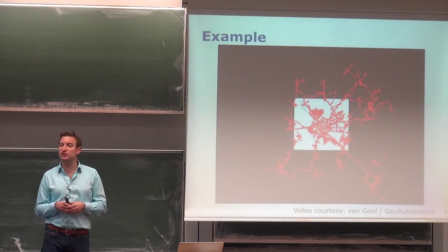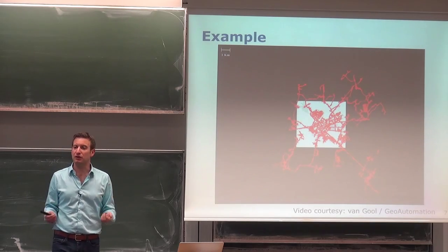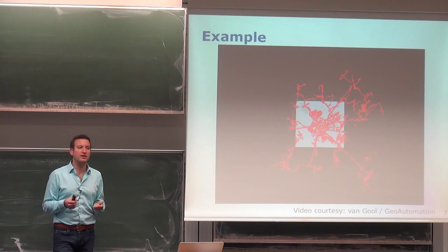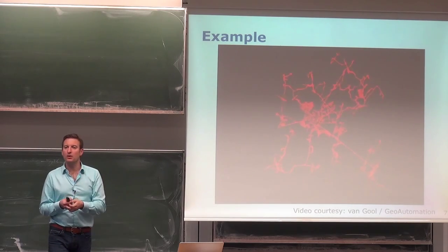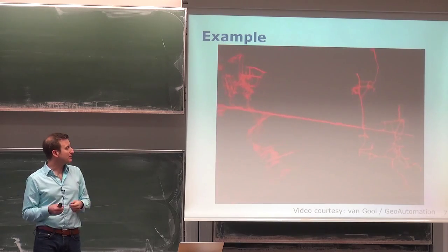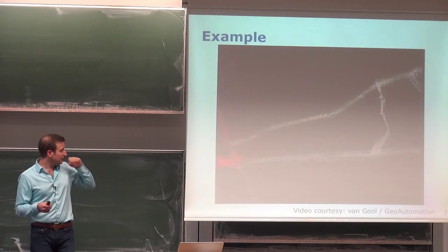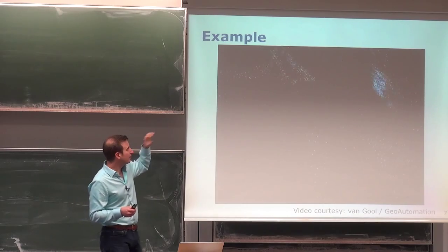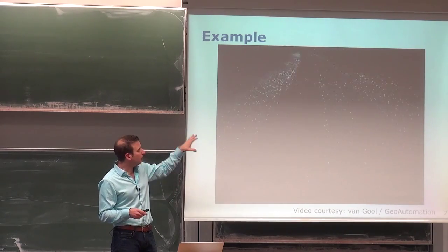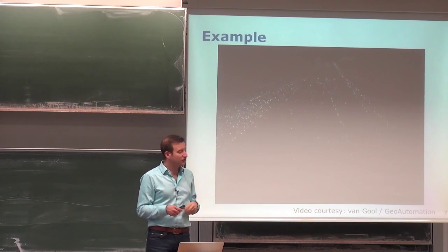So you will use additional sensors. You may also exploit the odometry information of your car. So from the speed of the car and the steering angle of the car, you can get an estimate where the next pair of 8 camera images have been taken. You can actually zoom in again into your model and go back to these point-based representations. So these points are the points scanned from the environment.